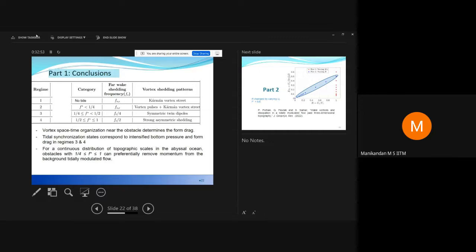And then your Froude number is basically the inverse of H divided by that length scale. If H becomes very large compared to that length scale, which means your Froude number is becoming very small, then one has to see what happens. People have done hydrostatic simulations, and they see changes in the vortex shedding frequency even at this Froude number of 0.15, but we don't.